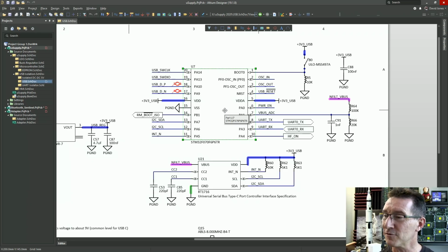But anyway, we've decided, bugger that, we're just going to put in a larger micro. And of course, Murphy's Law says that the package we chose, this 20-pin TSOP package, the largest part is a 32K part. So to get, say, a 128K part, we have to move to an entirely different package.